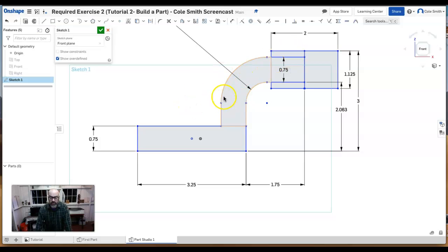All right, now here's kind of a fun one. This one's called a spline. So it's a little wavy line up here, 3 little dots. When I click on it, it's going to look like I'm just drawing a regular line. I'm going to draw a line from this point up to that point there. But you can see when I start moving around, it kind of is flexing on me. It's getting a little weird. It's because it's a spline and not a line. But I don't want to keep clicking now. I just wanted to make that one point-to-point line. I'm going to hit escape.